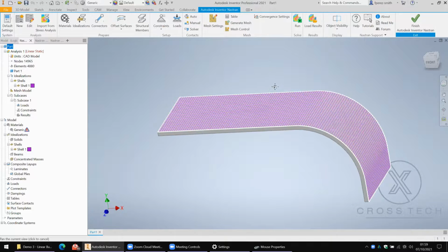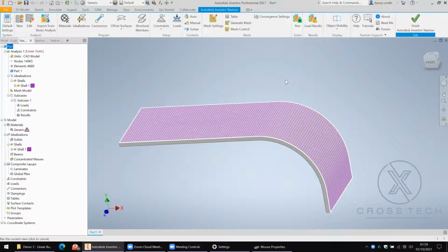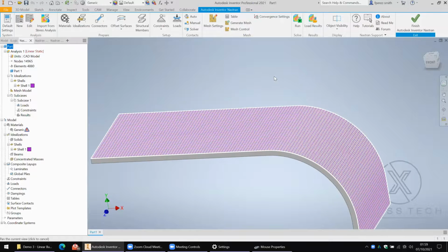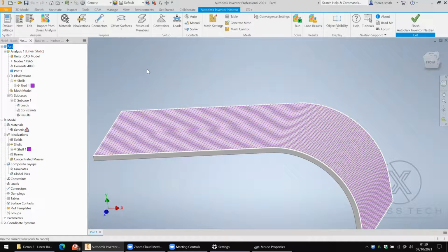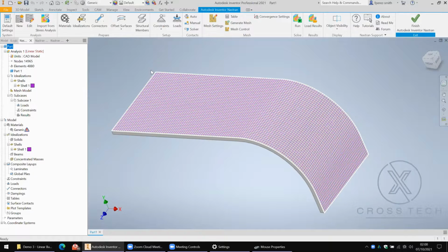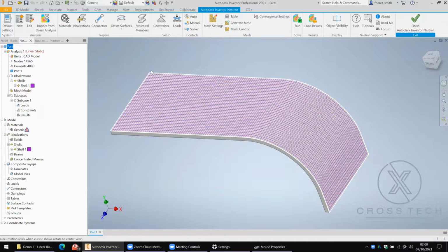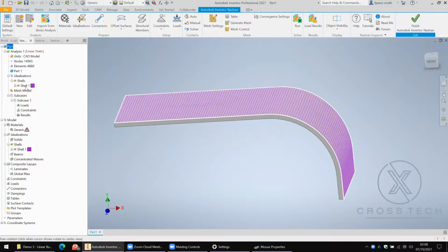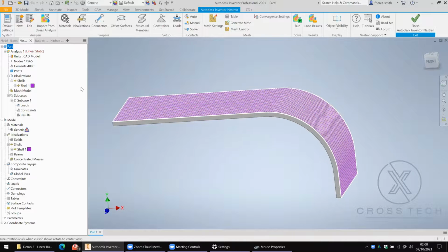If you had an infinitely powerful computer, sure, you could make solid meshes from everything. But if you're within the mortal realm, then shells are useful. One more very important thing before we wrap up. Shells sometimes get misused, because how do we know what direction the shell is going in? I'll put it back to its default. So we'll say advanced options, no midplane. We might say, shell's looking pretty good.